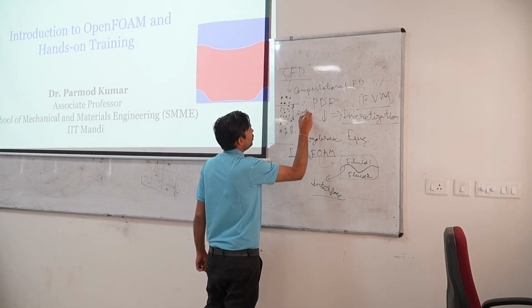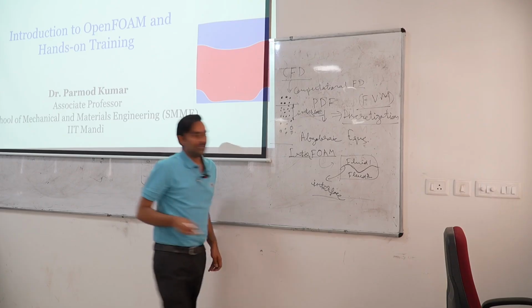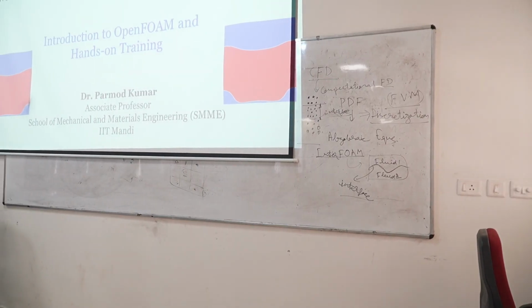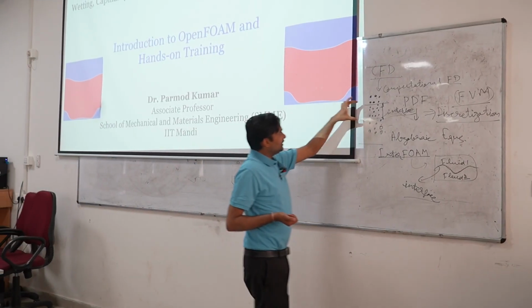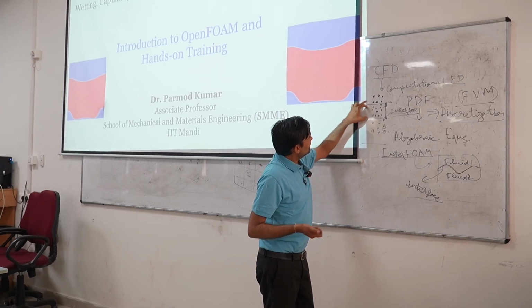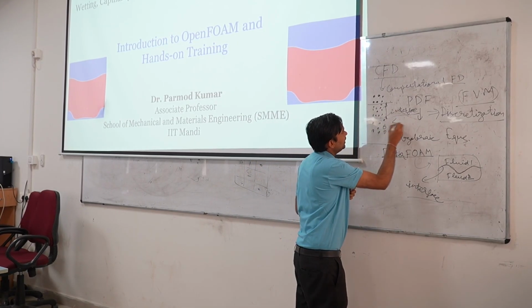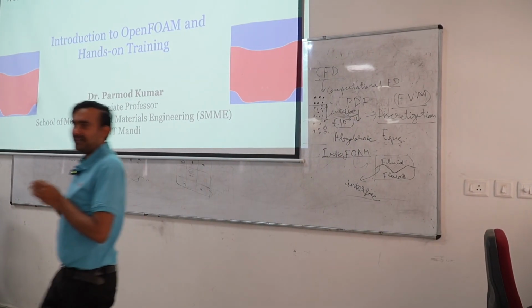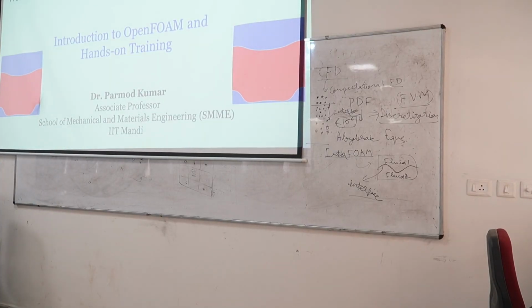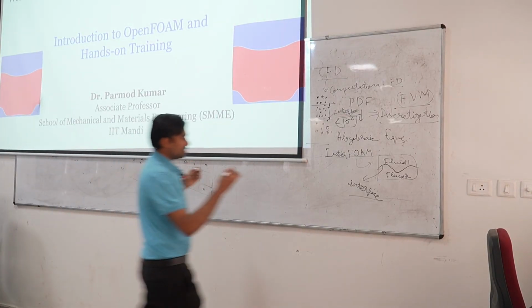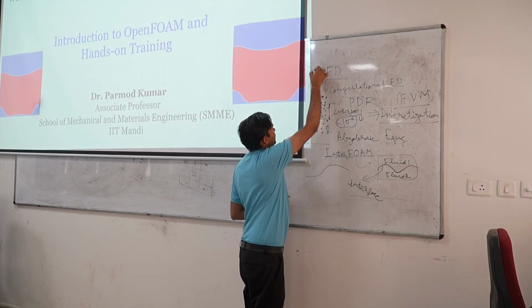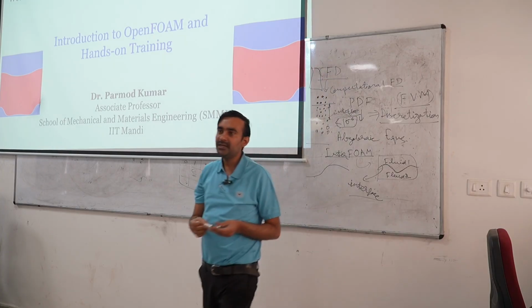So, if we see from a microscopic perspective, the interface typically has a finite amount of thickness. However, whenever we look from the macroscopic perspective, the length scale of this is less than 10 to the power minus 6, so it is less than even a micron. So, at the macroscopic level, we assume the interface for a two dimensional case to be a simple line, and for a three dimensional case we consider it nothing but a 2D surface.